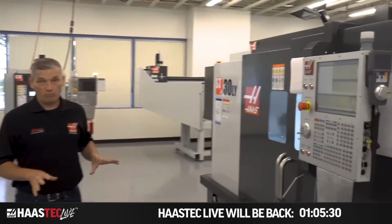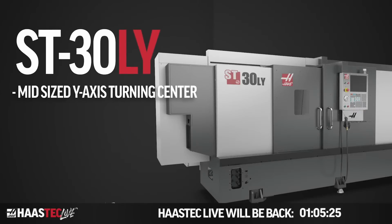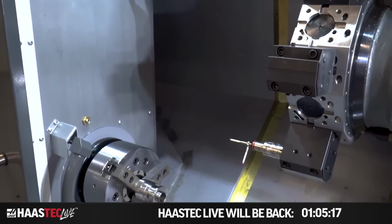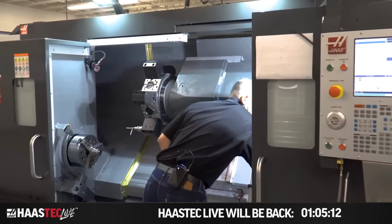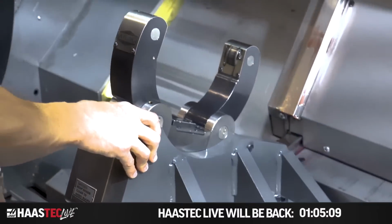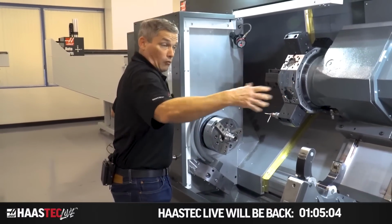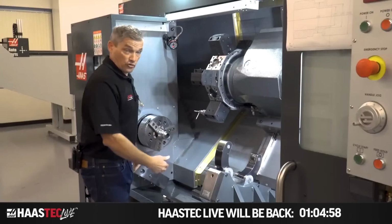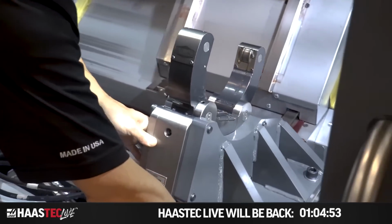So this is our new long bed ST30. ST30 LY, Y-axis lathe in this case. And of course, you're gonna buy this machine because you need to turn long parts, or maybe you need to turn intermediate length parts. And maybe you want to do that with our steady rest. So you're kind of in one of two situations here. Either you're gonna run a really long part in which you're going to support it by the tailstock, or maybe you've got an intermediate length part that you're going to support with your steady rest for doing deep hole drilling and end work on that shaft. Very easy to move the steady rest back and forth.